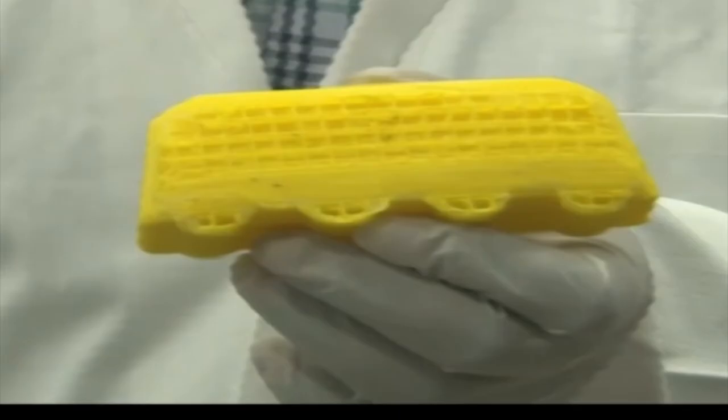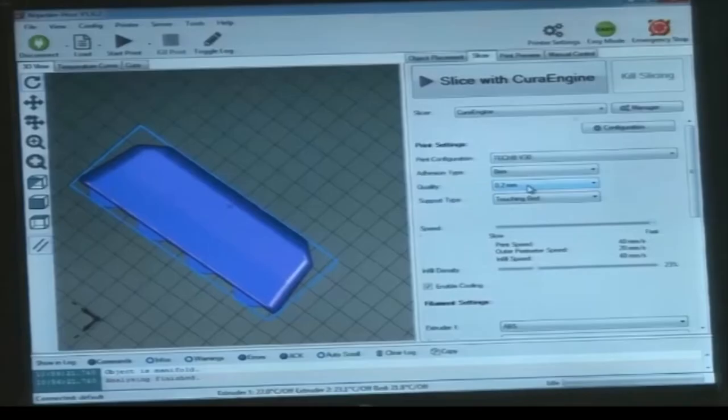In this case, only one spool is used, and both the model and the support materials come from that spool. That is why the color of the spool is obviously one, yellow only. So it is done by a single spool here. We can even have a support material that is a little cheaper, because the support material is not the final function that we need to provide. This is the potential, the beauty of FDM technology, that if there is any inclination or any pocket or any profile inside it, the machine will program on its own and deposit the material.